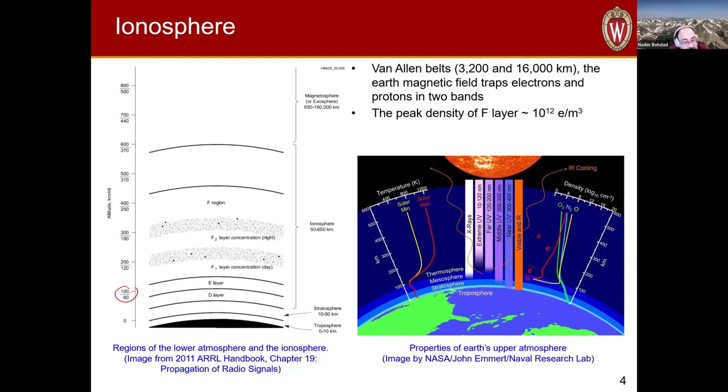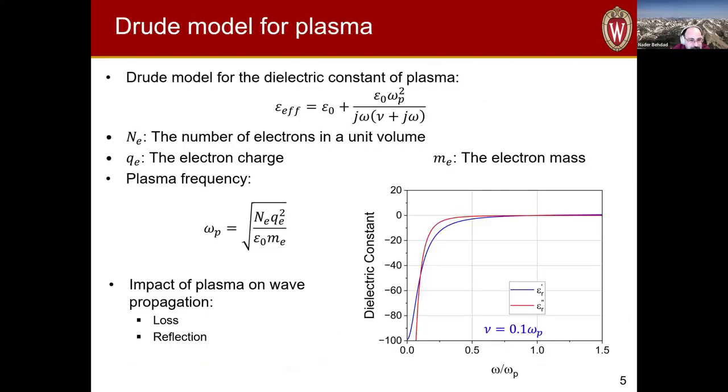That picture becomes a really interesting picture when we go to very low frequencies, the VLF, for example, let's say 100 kilohertz or 10 kilohertz or so, where now our wavelengths are significantly larger. Now the dimensions, the separation between the Earth and the D layer of the ionosphere, becomes comparable to the wavelength, and then it becomes a little bit easier to think about this as a cavity with traditional spherical modes.